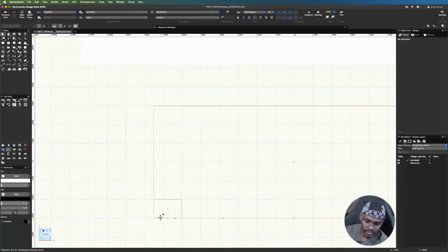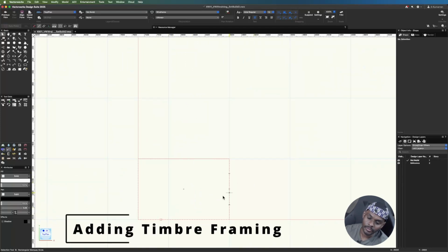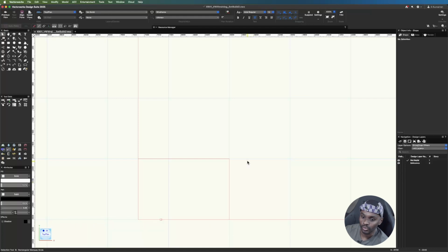Okay, and now I can zoom in over here to begin assembling my first block. I'm going to imagine that in the building of this set, it's going to be put together by 4" by 4" blocks of wood. So for that timber, I'm going to use the rectangle tool, for which the shortcut is the number 4 key on your keypad. If you're wondering why, it's because there are 4 points to a rectangle.